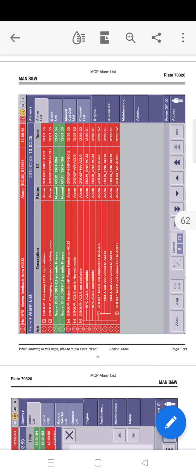So in the MOP panel, that is the HMI, human machine interface, there are 4 fixed areas. We can see what those are. The alarm status bar, which shows the oldest non-acknowledged alarm and alarm status at the top of the screen. A navigation bar at the right side of the screen, a toolbar at the bottom of the screen, and a screen area for the rest of the screen.